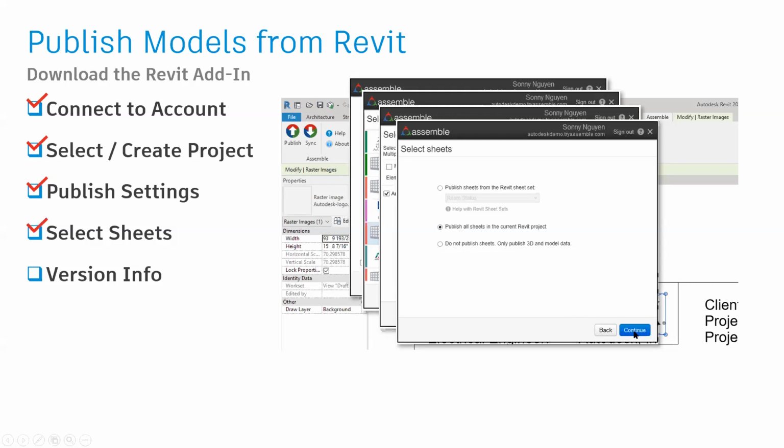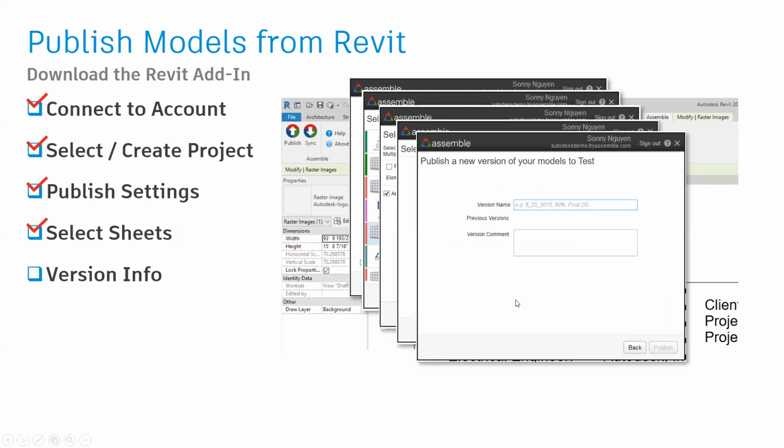Next, and finally, we can put a little bit of information into the version here. Anytime we publish a model from Revit into Assemble, if that's the first model, it's going to automatically call that V1. Any subsequent models would be V2, V3, V4, etc. Here you can also add a little more information to that version name. So in addition to Assemble automatically saying V1, V2, V3, you can say this is 50% DD or 100% DD or an ASI set, and you can also put a little bit of information into the version comment here.